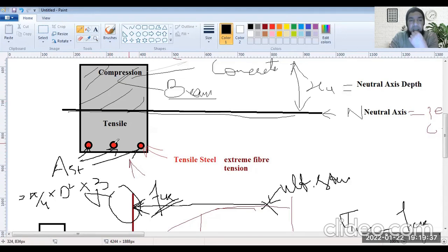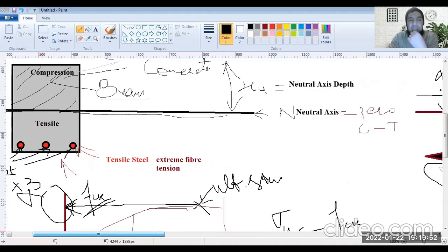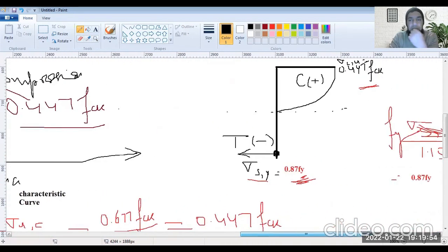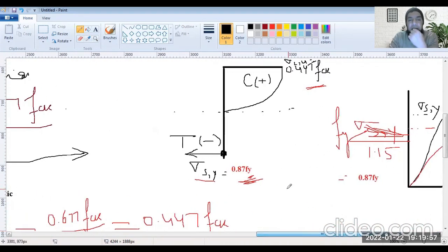When the section is cut, the diameter of each of these three bars gives the area. D is the diameter of each of the bars. Then you get the area of cross section of each of these steel bars, and added together you get AST. Because the cross section of these 3 bars is what resists the tensile forces. The cross section, the dia of these bars, is resisting the tensile forces in flexure.